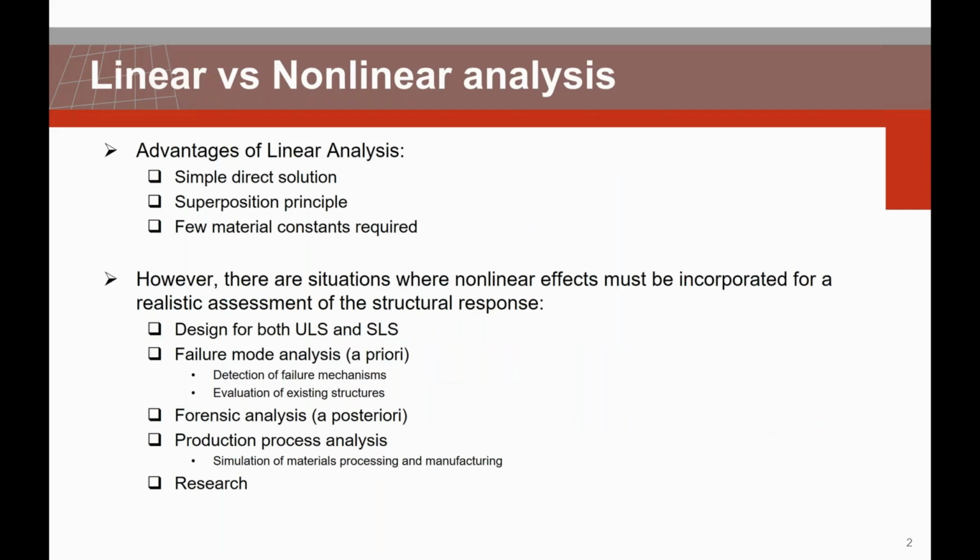A linear analysis has many advantages. A simple direct solution may be obtained with no need for costly load incrementation and iterative schemes. The superposition principle can be applied. Solutions for various load cases may be superimposed. And few material constants are required. The number of material constants required to describe a constitutive behavior is kept to a minimum in a linear analysis.